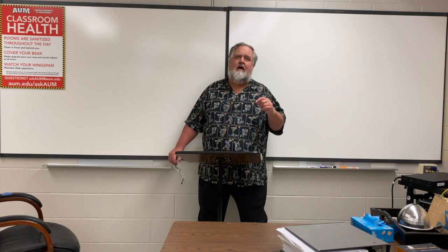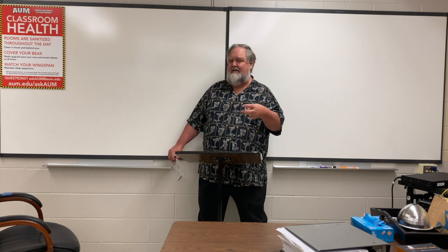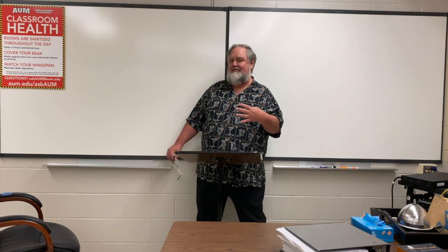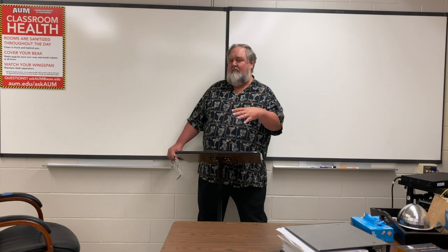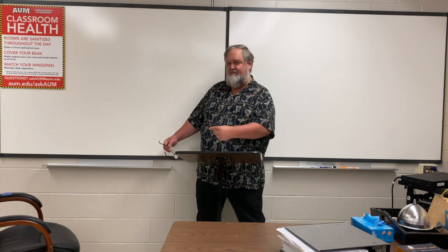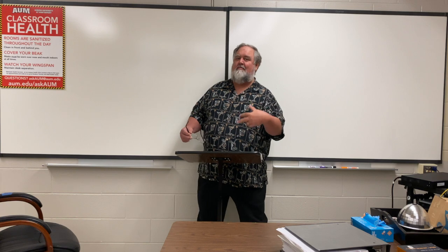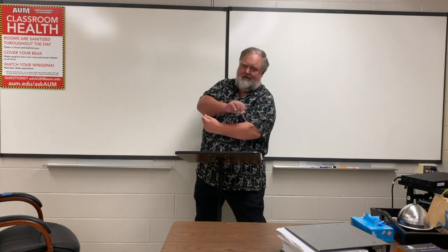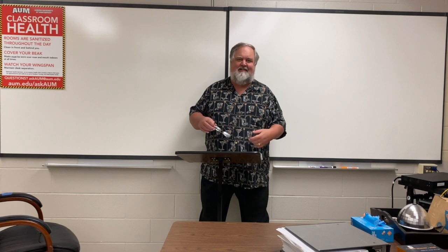Now, just so you know, a reel-to-reel tape has a head like a cassette tape, which you don't know what that is, or an 8-track, which you don't know what that is. But there are 4 tracks on reel-to-reel tape, 1 and 3 and 2 and 4. When you flip the tape over in the system, the head on the reel-to-reel only reads 1 and 3. So as 1 and 3 are going through this way, when you flip it over, 1 and 3 have now become 2 and 4, and so that's why you can have 2 recordings. You record something on this side of it, and you can record something on that side of it. Most people are only going to record on one side of the tape. But occasionally, you'll see something on the box, especially in the old days, that says something's on it, you can't find it, flip the tape over. It may be on the other side of the tape.